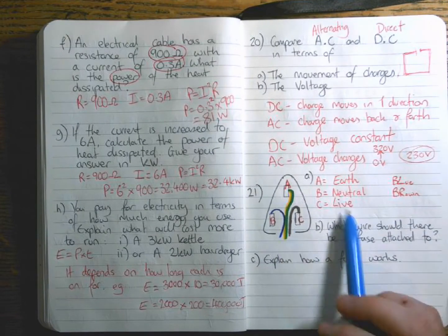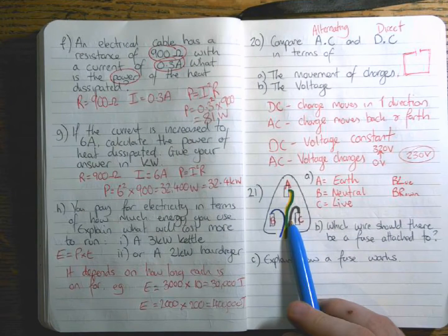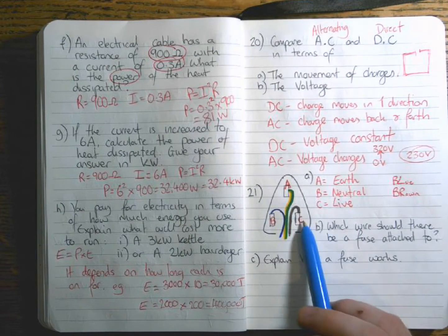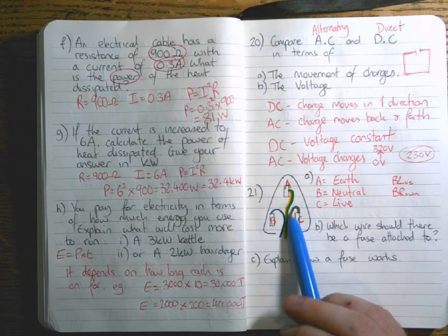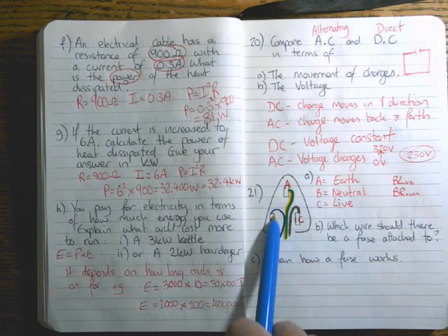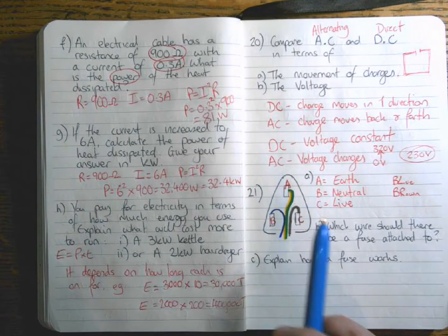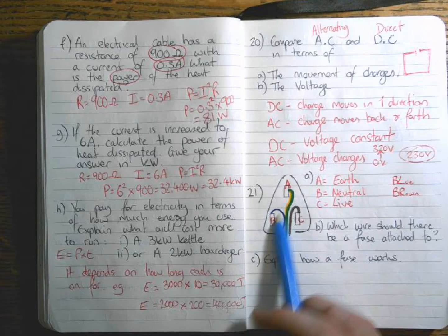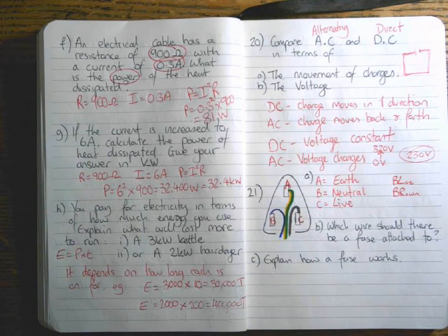I remember the brown wire because if you get electrocuted, because it's live, it's a slightly inappropriate way to remember it, but let's just say if you get electrocuted, there's a slight chance that you might brown yourself. Moving on, that only leaves the neutral wire to be blue. So brown, live, bottom right, blue, bottom left, neutral, earth wire at the top, green and yellow.